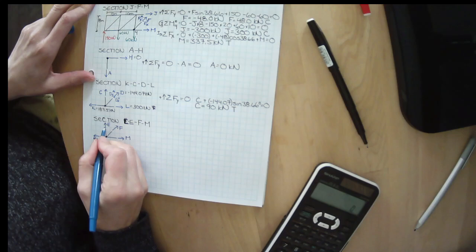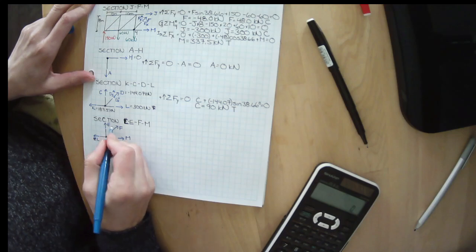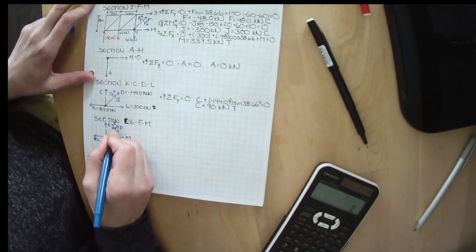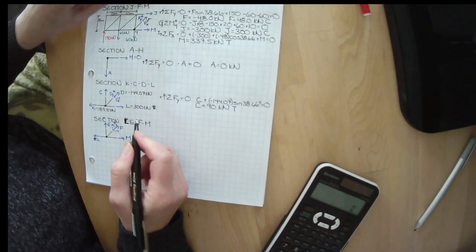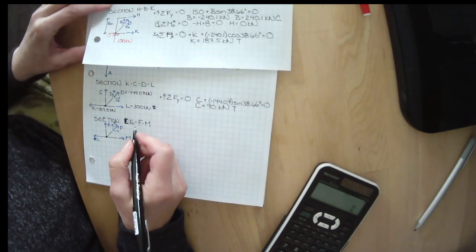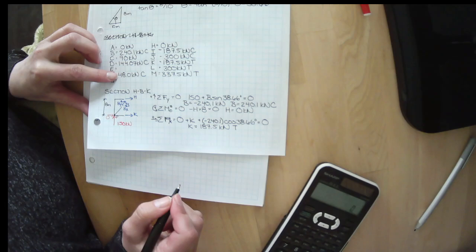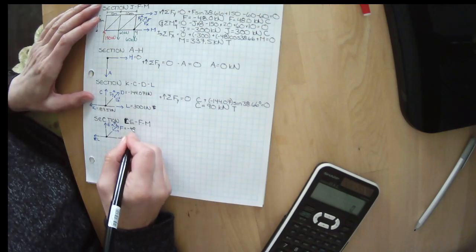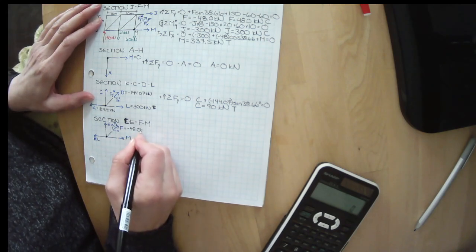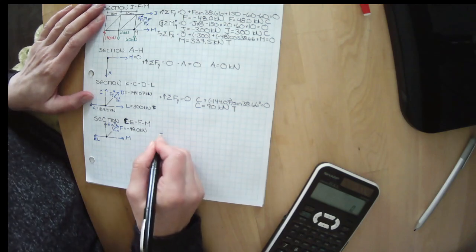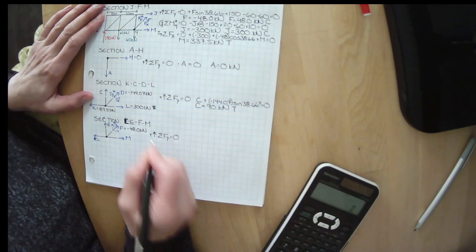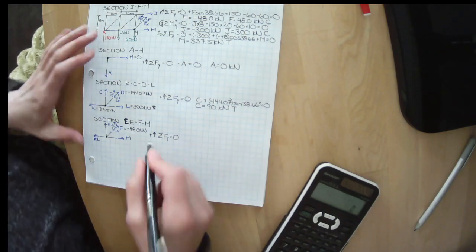Have you guys noticed that what I'm looking for is this one here? And so what I really want is Fy here. I'm just going to go ahead and only fill in Fy, or F. F, we found earlier, is 48 kilonewtons in compression. So it's minus 48 because I've drawn it in tension. We're going to sum our forces in the Y direction, where everything upwards is positive.